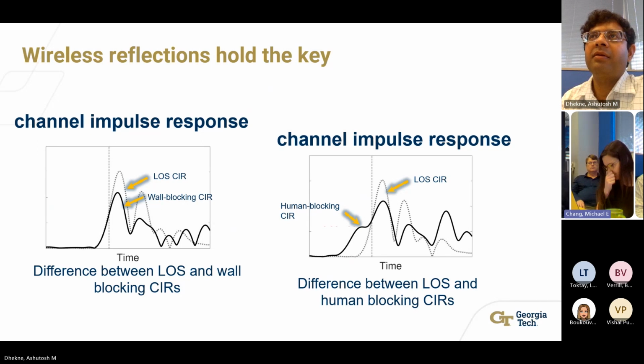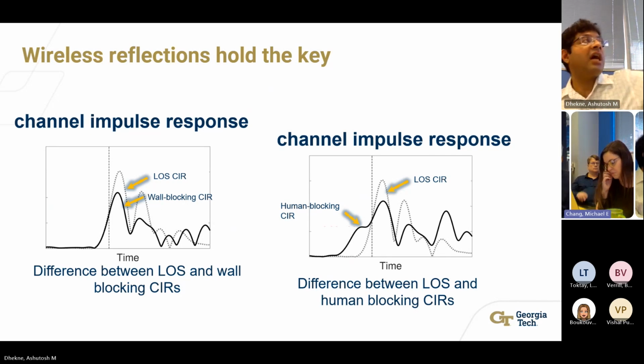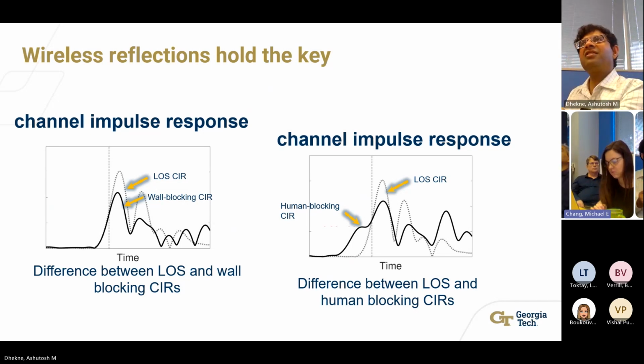Got it. And this graph itself is some product of triangulation and interpolation? This graph does not. This is a ranging scheme, measuring distances only without doing any triangulation at all. This is the lowest possible means of just distance measurement. And this graph is not a triangulation, but when you send a pulse, it goes and directly reaches the destination, which is this first peak.